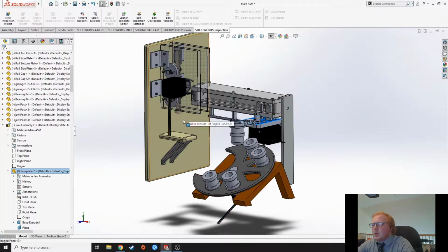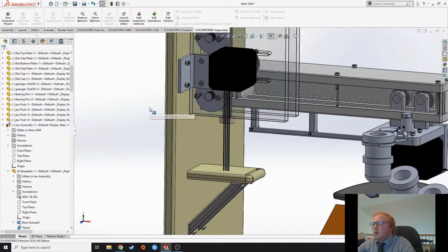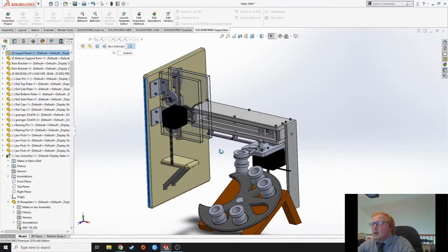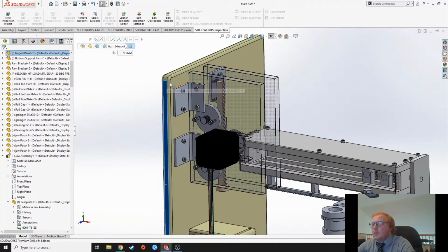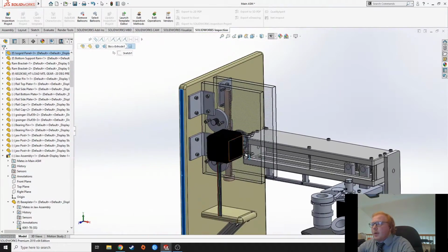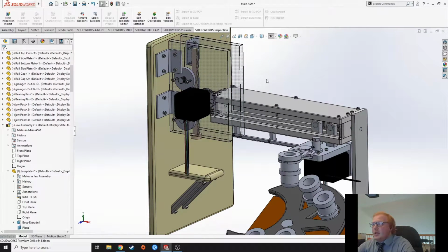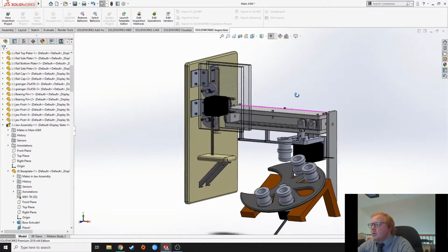tested. This isogrid panel originally was going to be an actual isogrid panel that's used commonly by NASA, but for the prototype we just adjusted the thickness of this material so that would provide the same amount of stiffness if it were an isogrid panel, rather than us machining one ourselves or buying it.